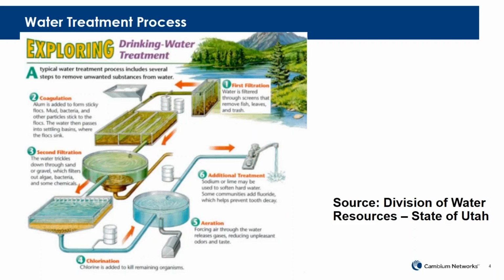And with the industrial Internet of Things, I can start to put sensors at every point in that whole process and start to not only take action to turn on and off pumps or look to see what the water levels or temperatures are, but I can actually start to do some second order analytics, where I'm looking at what the impact is and what the hidden signals are in all of that raw data coming back from those sensors, to optimize and improve the entire system. So again, that's just one example in the water space.